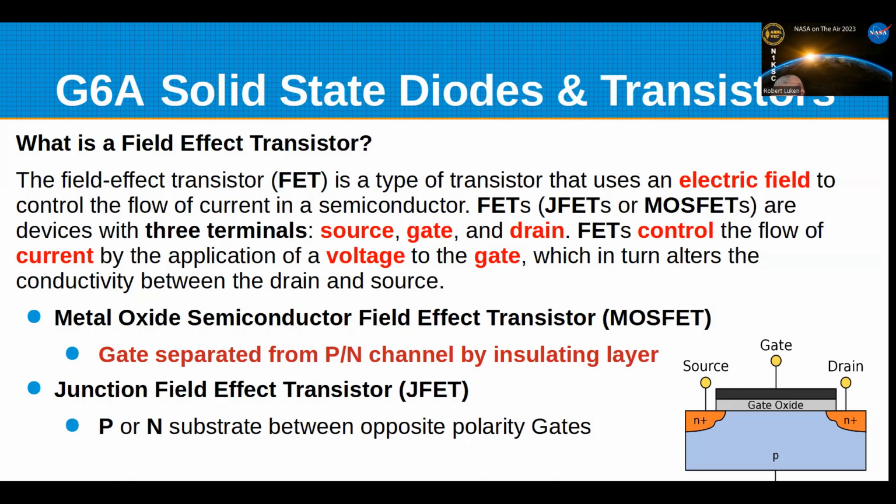They use gallium arsenide for high frequency transistors. A lot of times they'll use gallium arsenide as the base material as opposed to silicon. And there's some other exotic ones that get into the microwave type stuff. Typically, your common bipolars or FETs are silicon. We do use stuff like boron and phosphorus to dope the material to make it a P type or an N type.